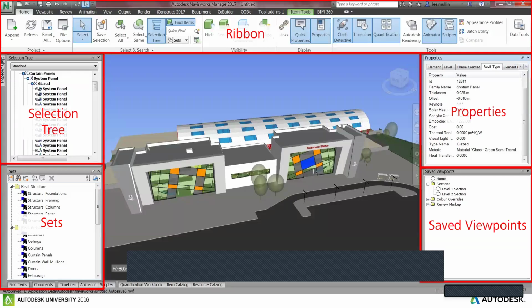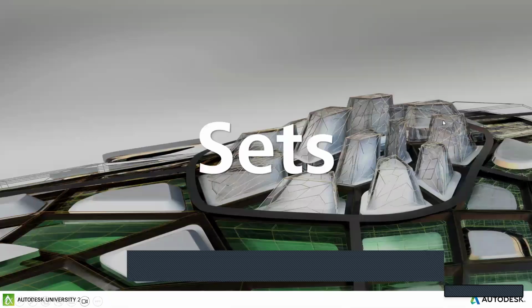Then there are two important things. One is, when you perform the clash detection, onto the left hand side you might see what all sets are there and what all files are available with us. So over here onto the left, it will showcase all those aspects. Onto the right hand side, once you select any of the elements, it will show the properties of the element.